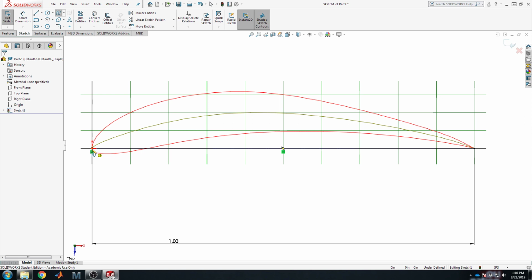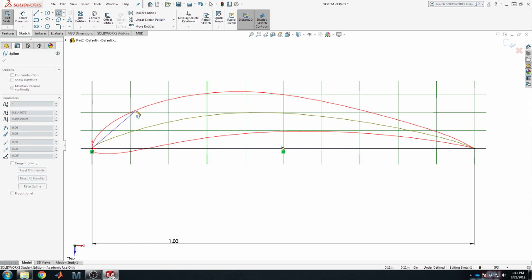Which endpoint, which derivative, which component of the spline algorithm is held constant or assumed to be 0 can change how the spline propagates, how many ripples you get internal to it. And really, in a solid modeling program especially, we want the surface to be simple, and we want the curvature to be simply represented. We want to minimize ripples and high-frequency noise that can cause a 3D model to break.